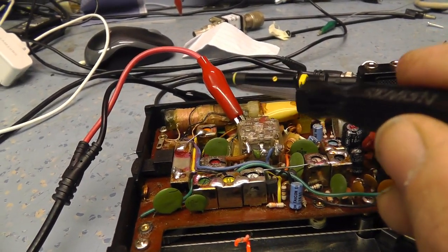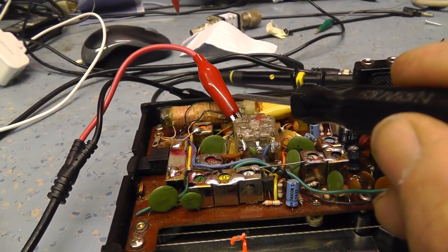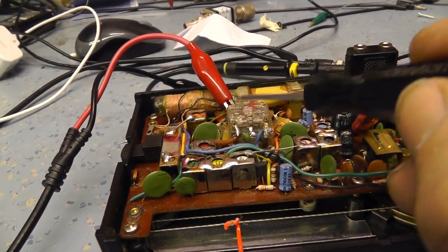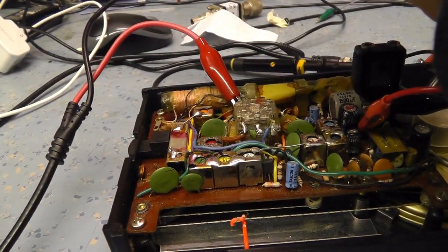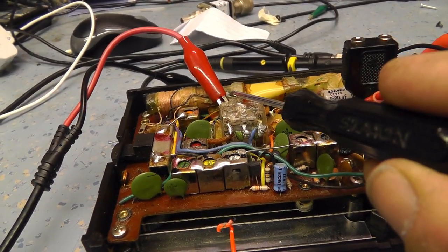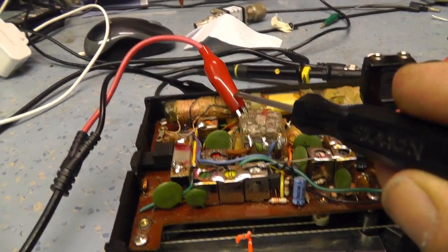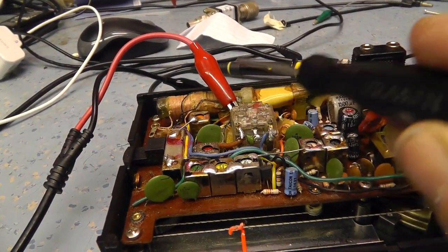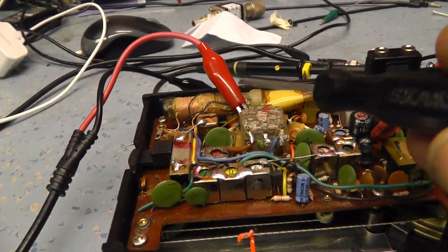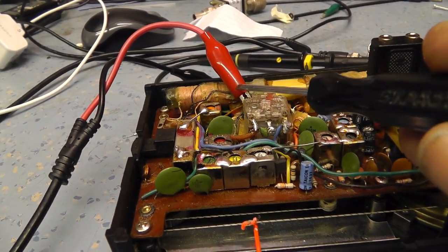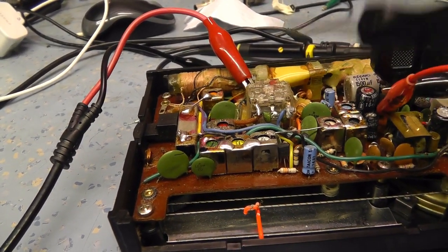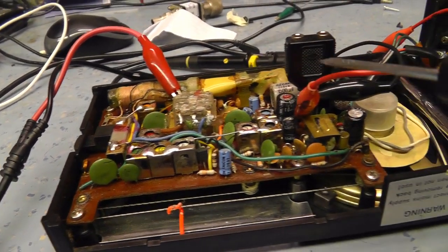So that's our RF signals coming in here, okay, and we're putting in the 10.7 swept frequency from the Wobbulator, so that comes into this point here. The ground connection is actually not connected at all, and you can actually just loosely couple this. If you've got an FM radio, you can actually just wrap that around the FM aerial. That works quite well as well. I could have connected it up to the FM aerial. I tend not to try and make physical connections to a radio unless it's absolutely necessary, or the instruction manual says it, and I haven't got the manual for this radio.